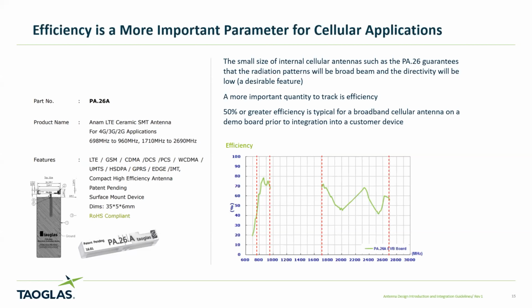Well, again, I think you'd probably get a more relevant answer from the people on this call. From an antenna perspective, we could design a single wideband antenna that would allow you to cover the frequency ranges you pointed out, GPS, Wi-Fi, the cellular bands. One of the problems is that if that single antenna winds up having a single feed port, you need to do the filtering out to the different radios. And as soon as you do that, either diplex out to the different radio systems, you start to incur losses for one. So there are some problems with trying to replace a handful of antennas with one.